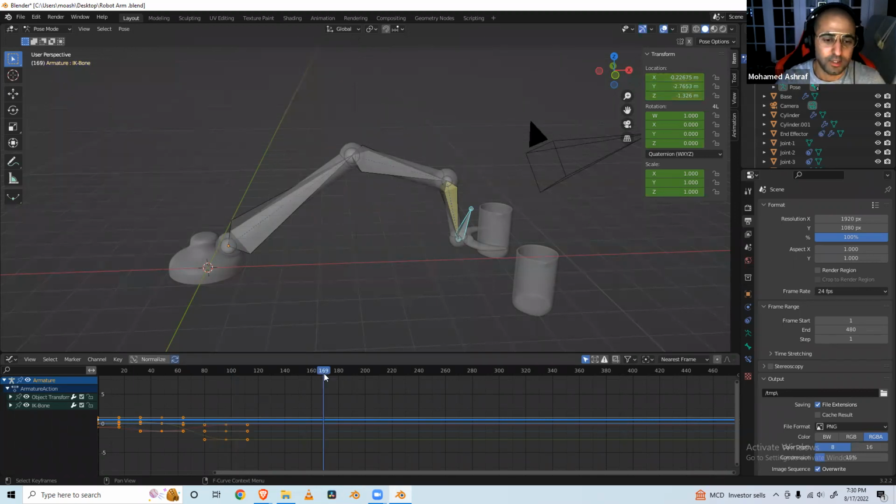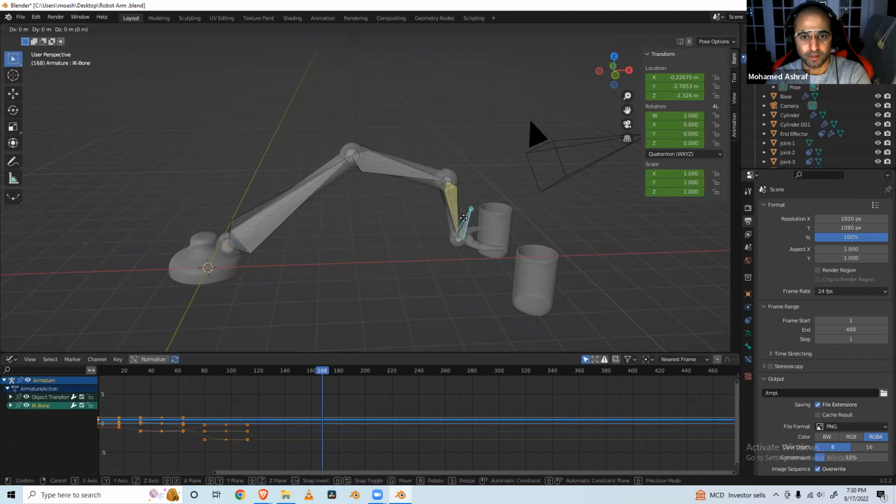Okay, 168. Let's say that within those 3 seconds, we give the end effector enough time to actually grab onto the beaker and situate itself the way it needs to. And so after 3 seconds, we move up. Actually, let's press escape. Let's go back. Let's say you have 1 second.